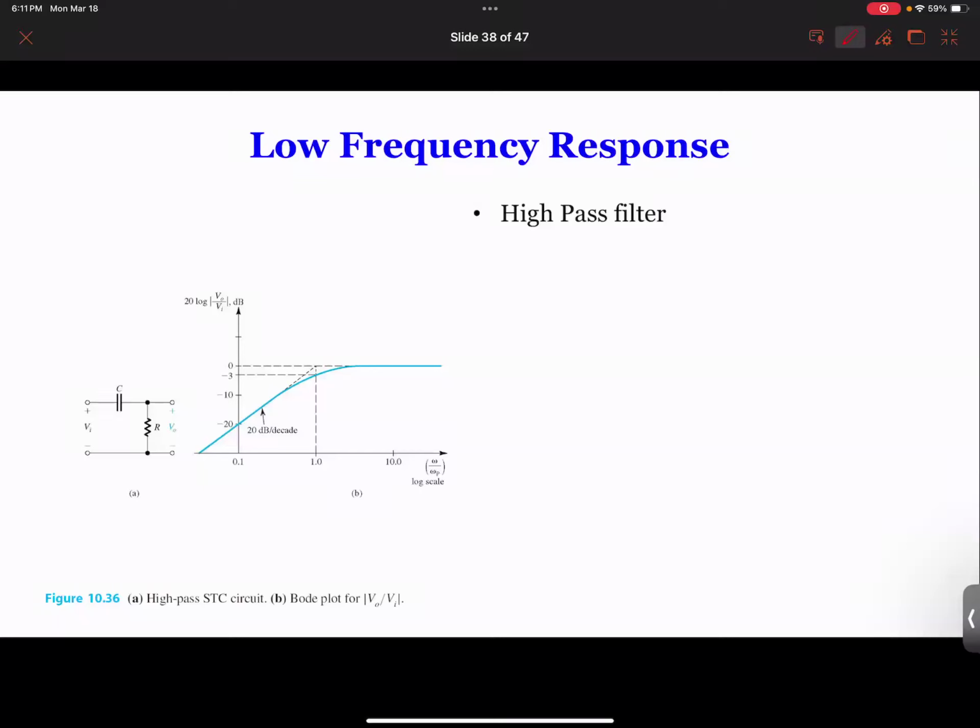For example, if you take an ideal MOSFET device with no capacitance, it's not going to give you the high frequency band drop. In that case, you need to use an extra device. Or if you use the ideal device, you can manually input CGS and CGD. Also for the BJT, it's CBC and CBE, okay? So you can input those numbers. And for the low frequency response, of course, you have the external capacitance. You can try to change the capacitance, and you see how your low frequency bands start to change. Okay, so those are the interesting things you can do.